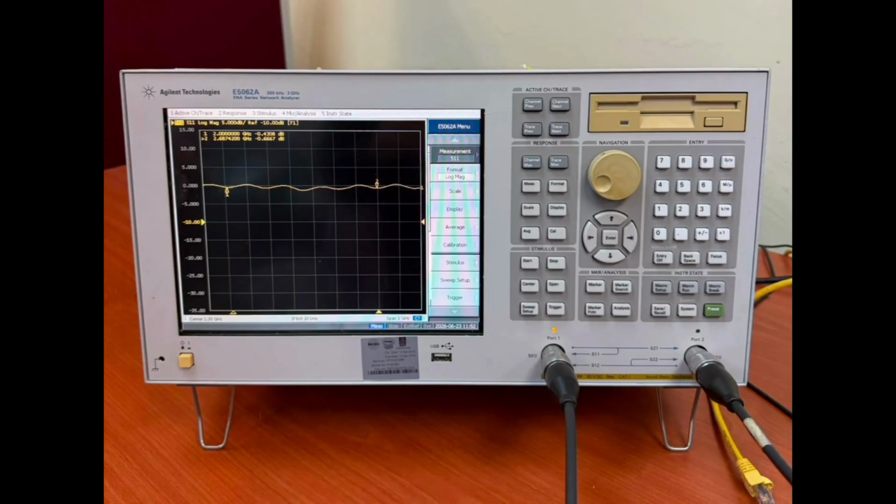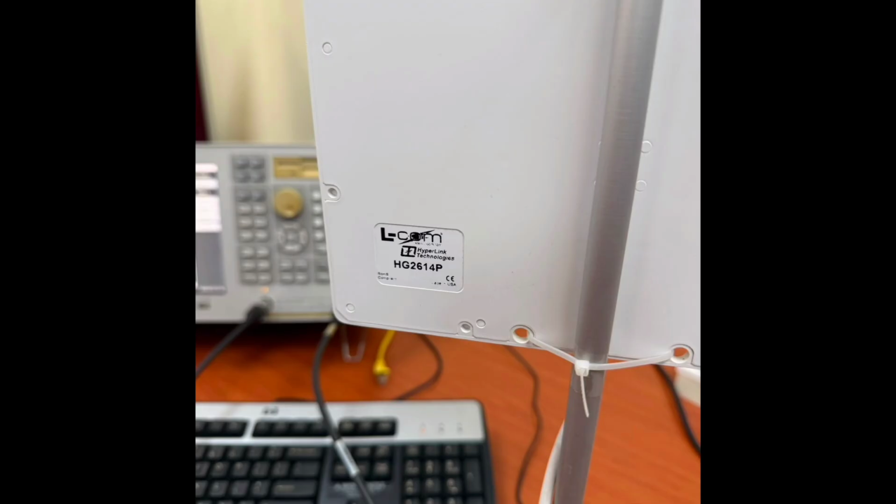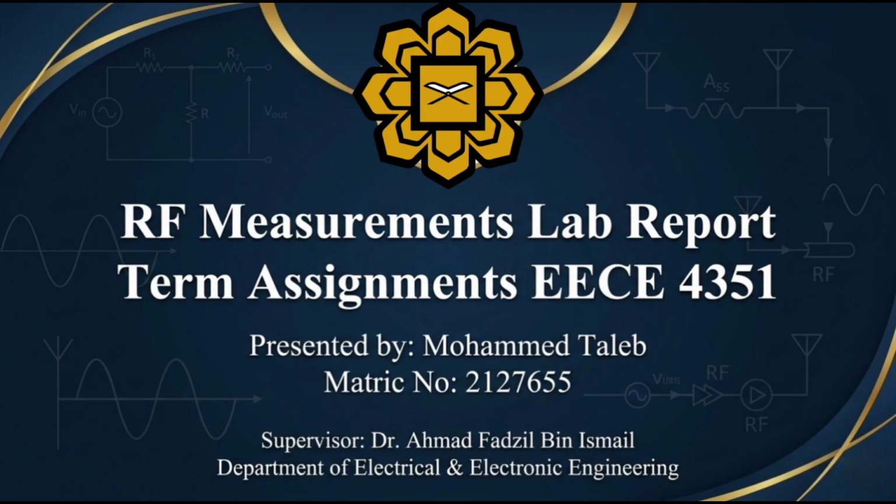Then we varied the output power to minus 20 dBm, minus 5 dBm, and 0 dBm, and observed the changes on the spectrum analyzer. We also changed the frequency to see the shift in the spectrum display. This helped us understand how the spectrum analyzer visualizes signal characteristics. We must always be careful not to exceed the maximum input power of the spectrum analyzer, and we start with low power to protect the instrument.